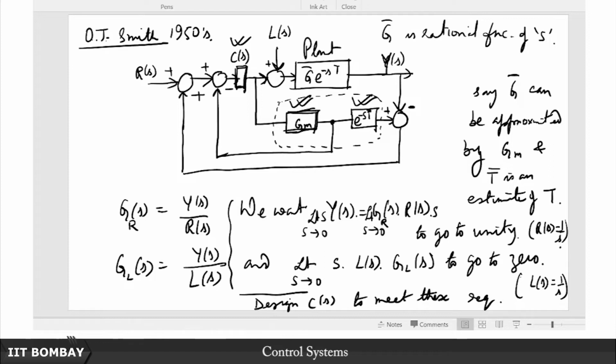requirements. Now, you see immediately the first thing that you are faced with when doing this is, of course, to convert this to a unity feedback equivalent. You already have that unity feedback as a matter of fact. So, for instance, if you just focus on this part, remember because of the sign reversal here, this is basically a negative unity feedback, even though there is a plus sign here, but because there is already this negative sign here, this is tantamount to a negative gain, okay.